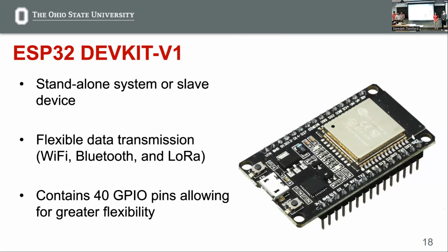The current microcontroller that we're using for our prototype is the ESP32 DevKit V1. It is practical for the final solution as well. It has built-in Wi-Fi, so it would not need to rely on the Wi-Fi at OSU. It also has Bluetooth accessibility. So if we wanted to access data from the ESP32, if we connected to the Wi-Fi server or the Bluetooth of the ESP32 module, you'd be able to gain access to how many cars are in the lot, which is the data that we're presenting.